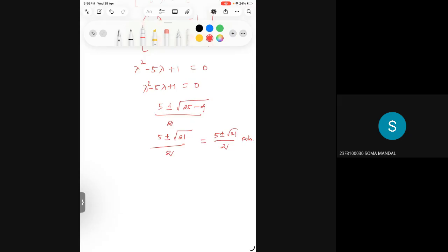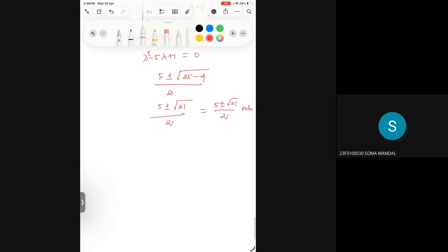Unstable, right? Okay. Then comes another point. The rule is, if you are asked to design a controller, you have to find the controllability matrix. You cannot just straight away go and find the controller, because even if the question is not asking for it, it's your rule to find the controllability matrix and see whether it is full rank or not.